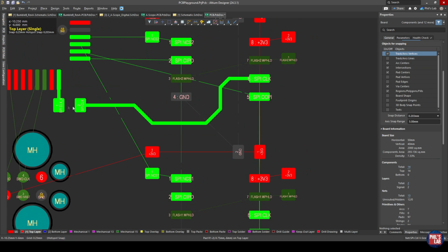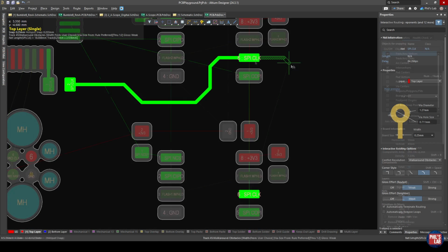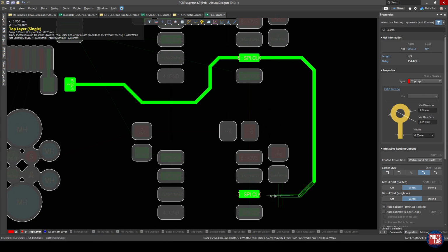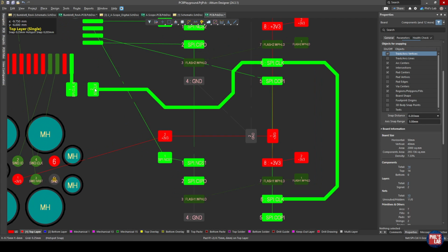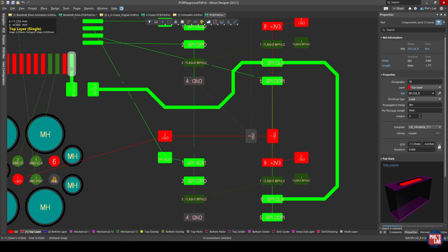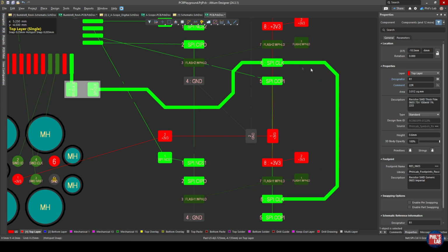What I prefer to do is I route out my output driver into my first device. Now, if this is the top or the bottom, it doesn't really particularly matter. Out of that device and then into the clock of the other peripheral. So in this way, we don't have this kind of branch or tree topology. I'm routing through in somewhat of a flyby topology with my series termination resistor to start with. So output driver, output pin, series termination resistor, through the devices.